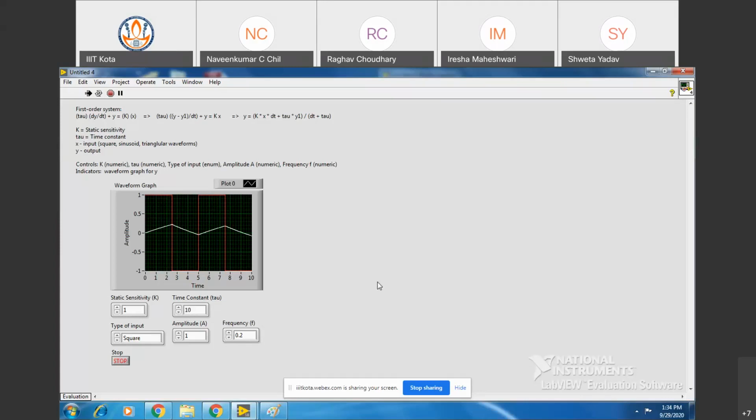if you remember one property of this low pass filter, or a first order circuit, it is a low pass filter. So if you keep the time constant very high, then what is the output you'll be getting? The output will be nothing but the DC value of the input. Now if you see, what is the DC value of the input presently? 0. It is 0, na. So if I make it 100, so just see, this is almost around 0.